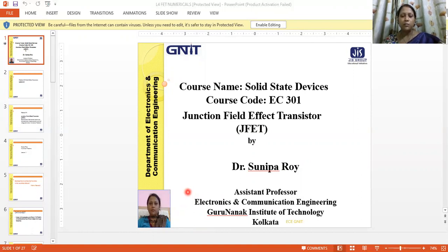Till the knee voltage is reached, and then the nonlinear region, actually it is the region where ID increases at inverse square law rate up to point B, which is called the pinch-off region. As we know, what is the pinch-off region? This point does not signify that the current is off, rather the current is maximum at this point.